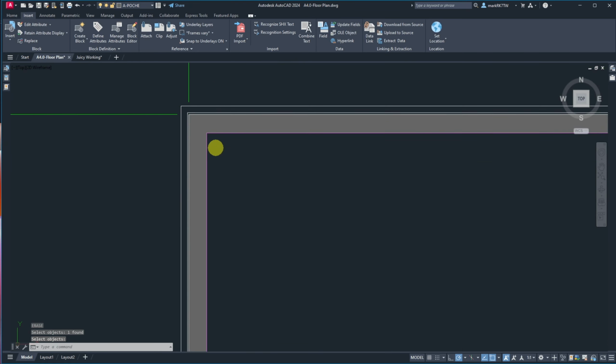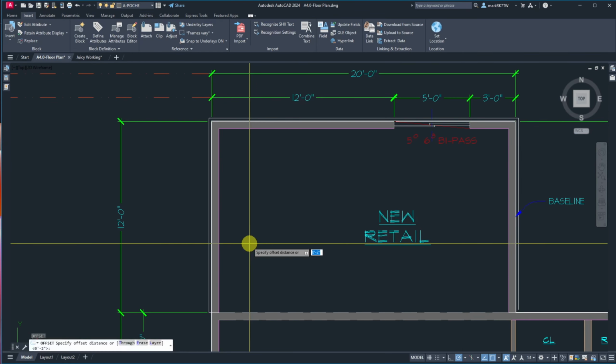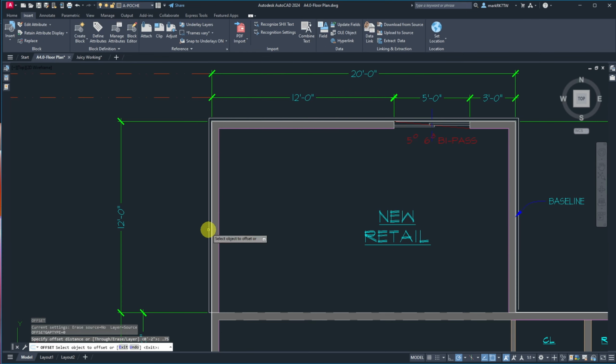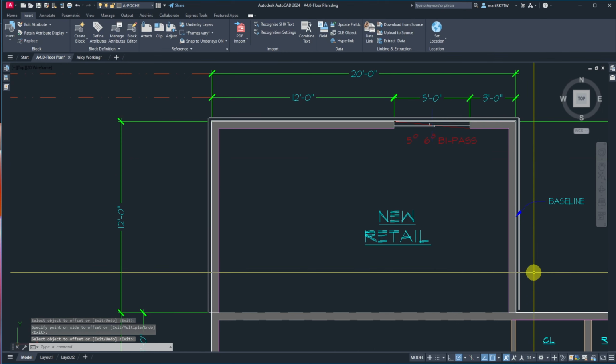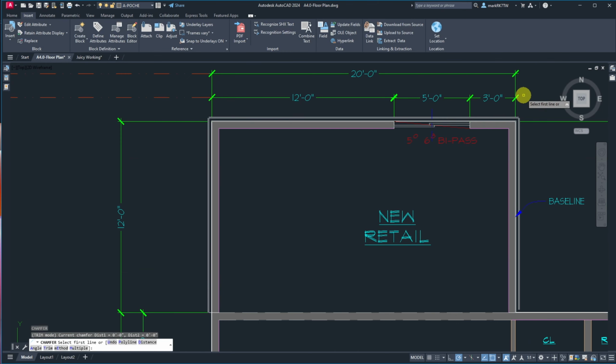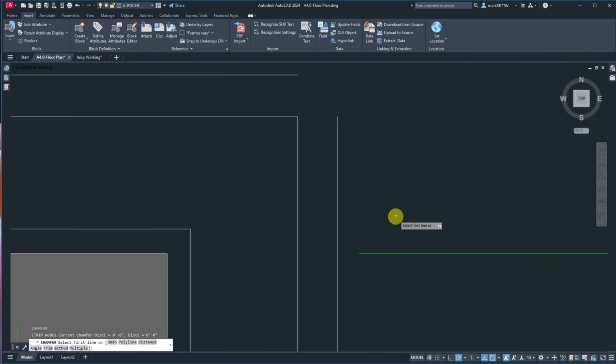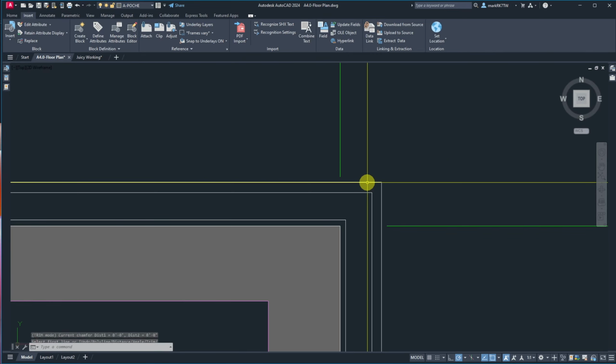Now, outside of that, I need to have something to hold that on with. So it's 0.75 to put battens every 24 inches. And for the plan view, I just show that as a continuous line and don't show every batten.